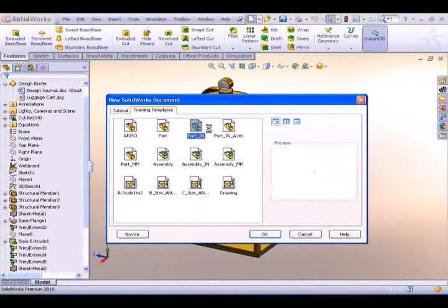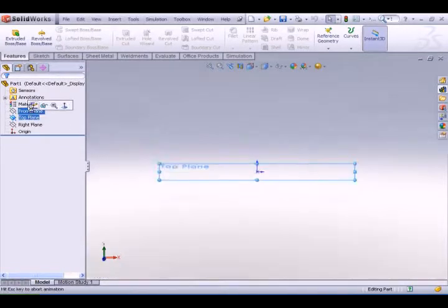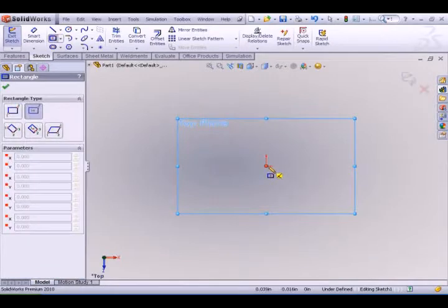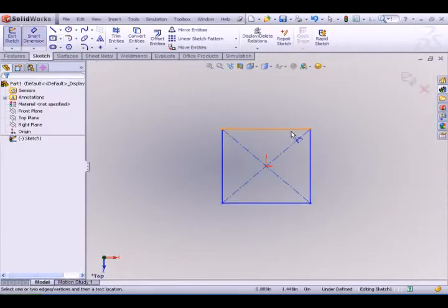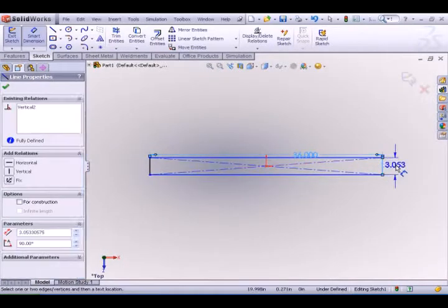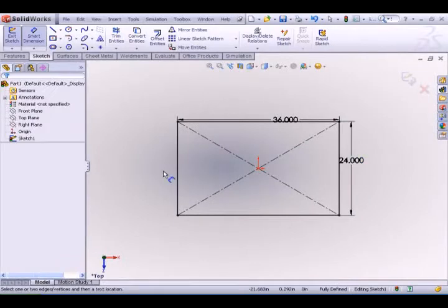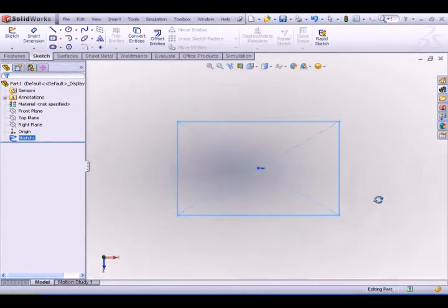So what I'm going to do is go through a couple different examples with you and show you some strategies to work with 3D sketching, as well as some of my favorite ways of working with it. Now the first strategy is basically stacking two-dimensional sketches. When you're stacking two-dimensional sketches, you start out by simply drawing a sketch, and that first sketch is going to be on a single plane. For instance, I'm going to draw the base. It is very easy to draw a two-dimensional base on the top plane.